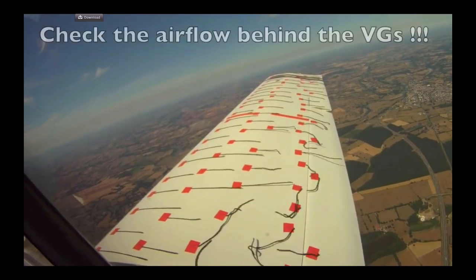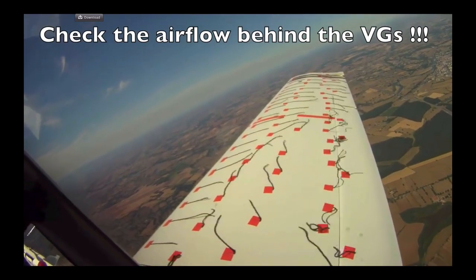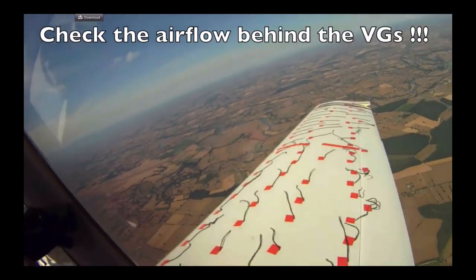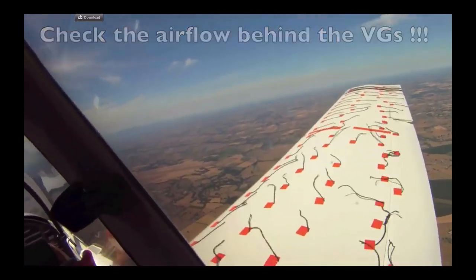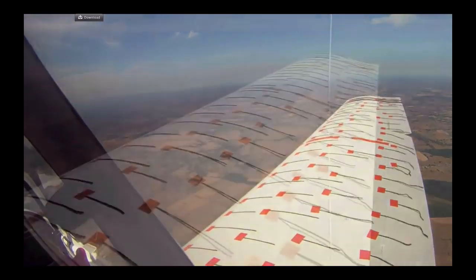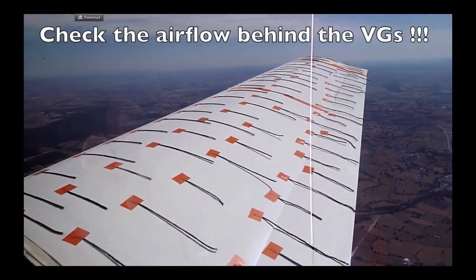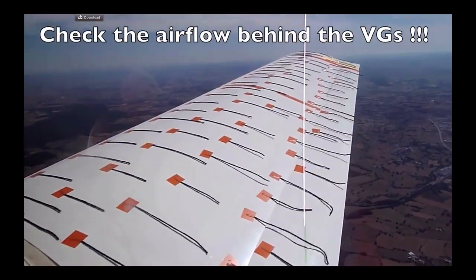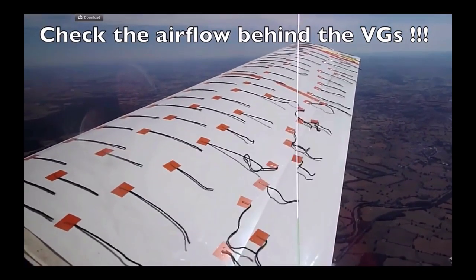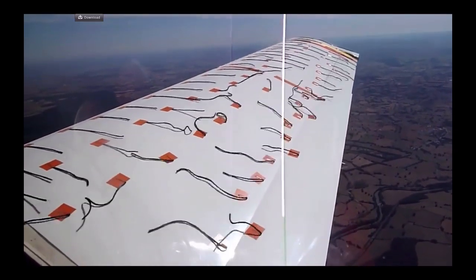Okay, so we're still talking about external flows. To follow up from last time, we had this discussion on lift and drag, which are really two sides of the same coin in some respects, in that they are both about forces induced by either pressures or viscous shear, and it just depends on which orientation we're looking at. Lift being perpendicular to the direction of the far field airflow, which would be horizontal in this case.